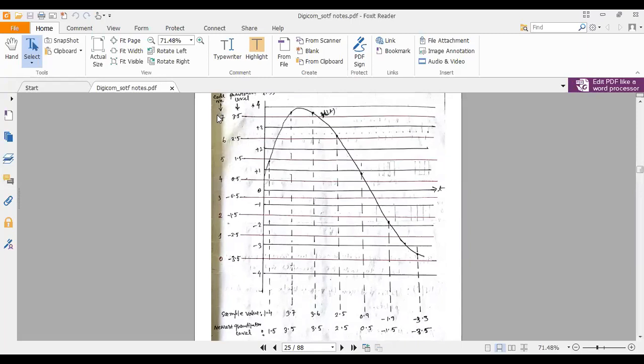कोड नंबर देना पड़ेगा. तो पहला वाला क्या है? 0 है. सेकंड वाला 1 2 3 4 5 6 7. In that way we have given all the code numbers. Okay, so each and every sample value का कोड है. -3.5 का कोडिंग कर दिया 0, -2.5 पोजीशन में जो क्वांटाइजेशन लेवल था उसके लिए 1. इन दैट वे 3.5 में जो क्वांटाइजेशन लेवल है उसका कोड नंबर 7 मिल गया.